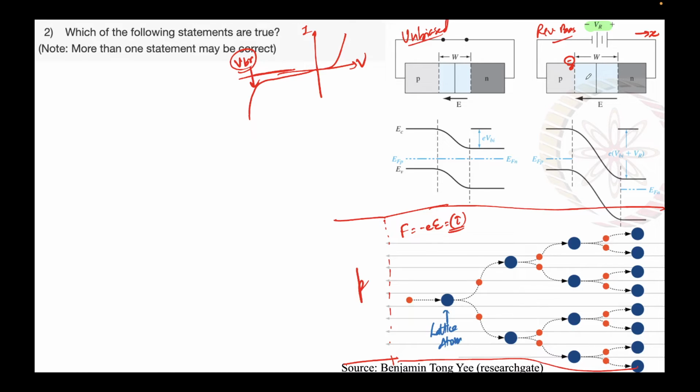Now it can happen, because please remember this depletion region is usually very wide, a micron or so. So this electron that is traveling in this direction will gain some velocity. Why? Just apply your classical mechanics: v equals u plus at. Even if the initial velocity is 0, after a certain point of time, or v squared equals u squared plus 2as, even if u is 0, this acceleration is nothing but force by m effective, m star, and s is the distance traveled. So this is the distance traveled I'm talking about, s, when this electron will encounter a lattice atom.